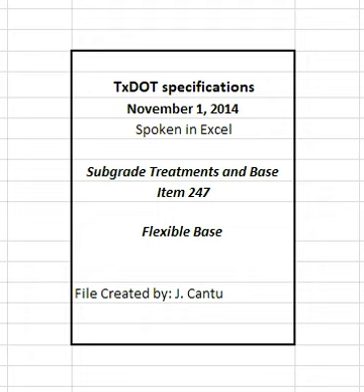Correct 0.1 mi. sections having an average international roughness index, IRI, value greater than 100.0 inches per mile to an IRI value of 100.0 inches per mile or less for each wheel path, unless otherwise shown on the plans. Reprofile and correct sections that fail to maintain ride quality until placement of the next course, as directed. Correct reprofiled sections until specification requirements are met, as approved. Perform this work at no additional expense to the department.